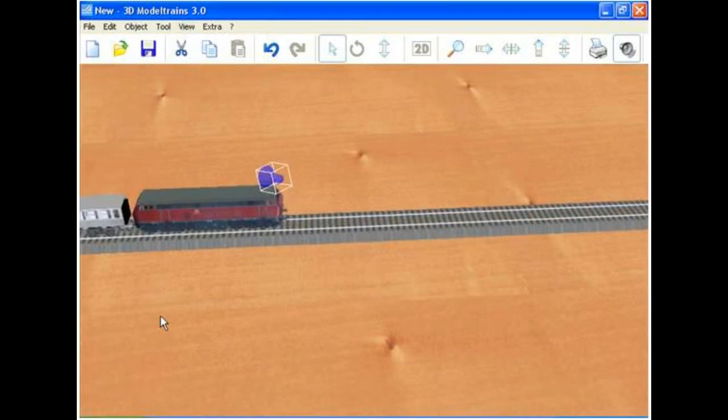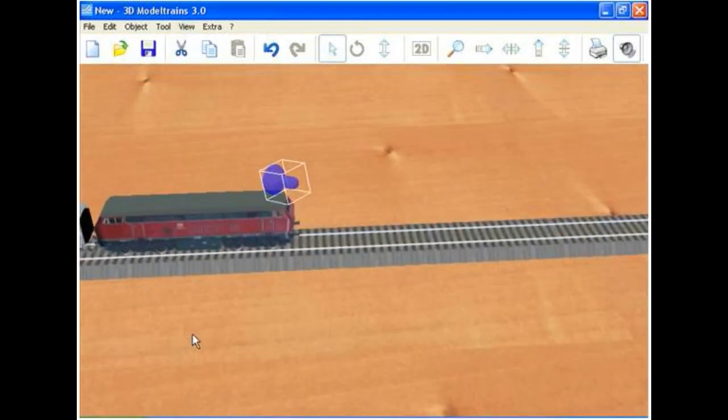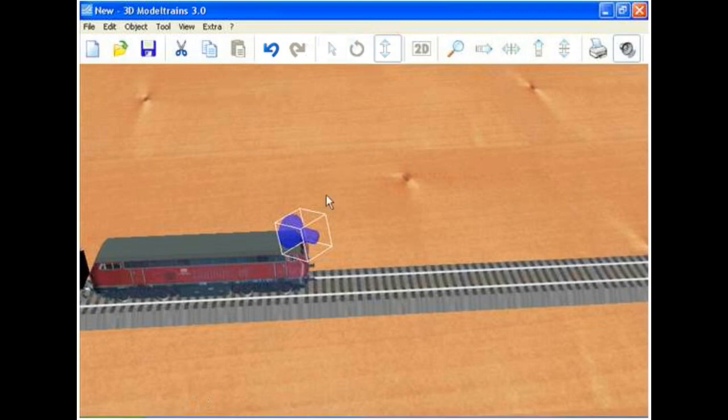Next, position the camera beneath the engine between the front wheels. Use the default Rotate Object and Object Height tools to move the camera. To orient the camera horizontally, from the Tool menu, select Rotate Object around X-axis.